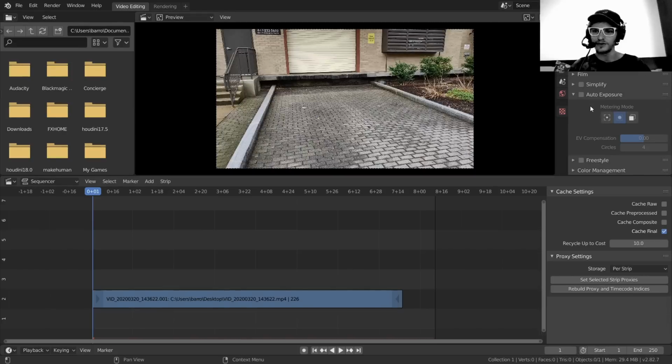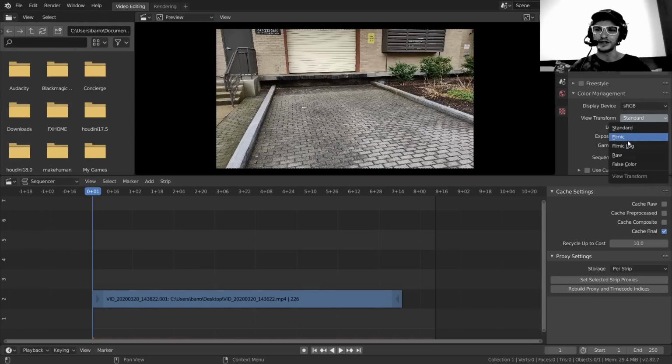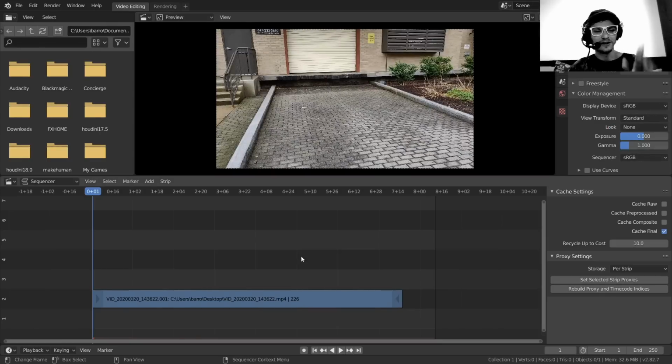And in the Render tab, you're going to notice under Color Management, we have Standard View Transform, which is something I always talk about, because usually you have Filmic and it makes it look weird, so Standard fixes that. But trim your footage if you want to, so I'm going to have it start on frame 1, and let's say instead of ending at 250, which is past when the footage ends, we can make it something like 200. Cool, so now we're going to have an image sequence from frame 1 to 200.